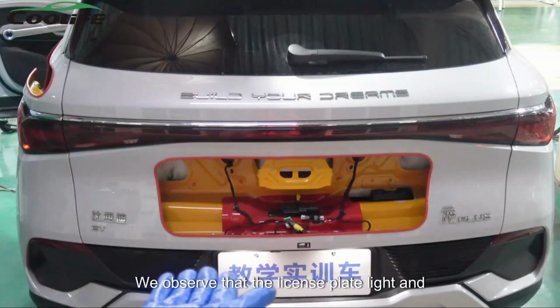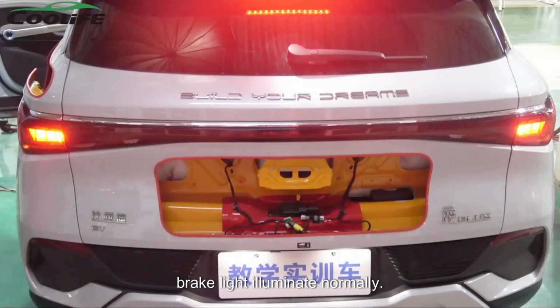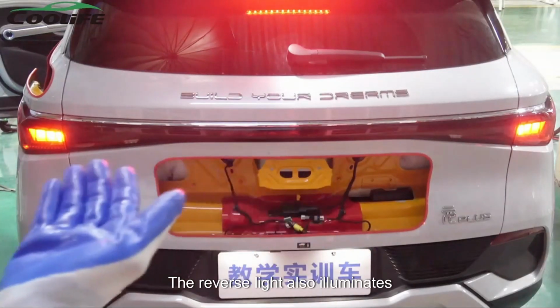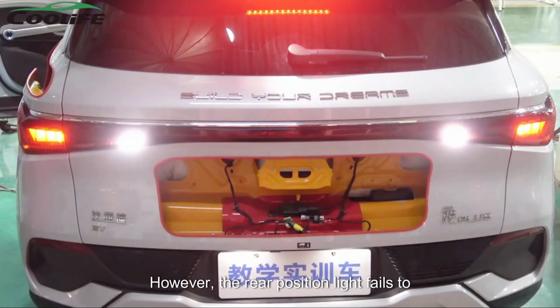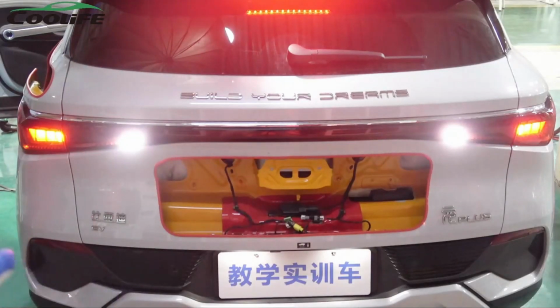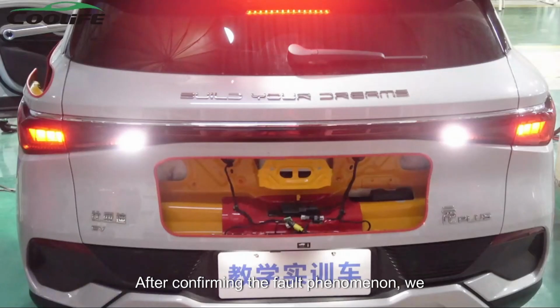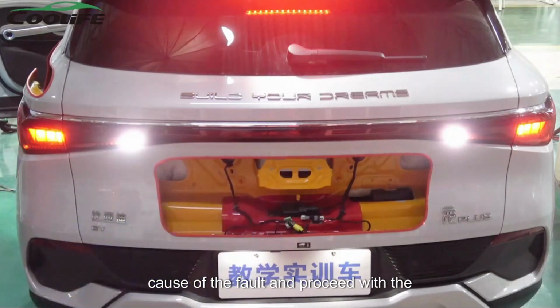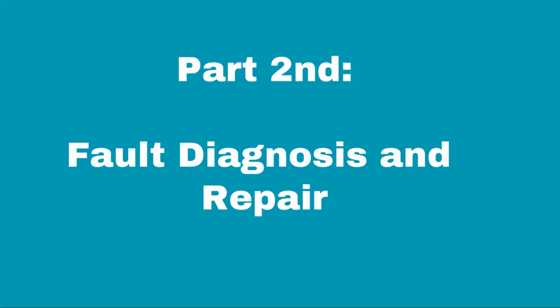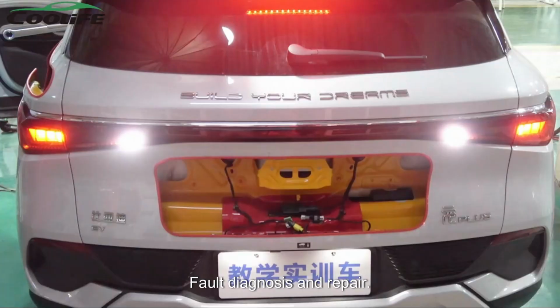We observe that the license plate light and brake light illuminate normally. The reverse light also illuminates normally. However, the rear position light fails to illuminate. After confirming the fault phenomenon, we will analyze and identify the specific cause of the fault and proceed with the repair. Part two. Fault diagnosis and repair.